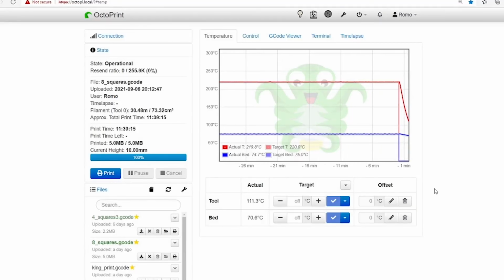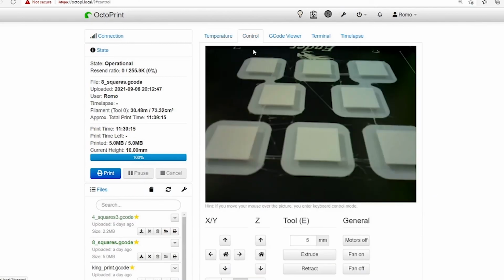You will see the temperature drop. As a general rule, just make sure the printhead is cooler than the build plate before you shut down. Go to the Control tab and turn off the light. Then turn off the printer itself. Confirm and you will see it gray out.